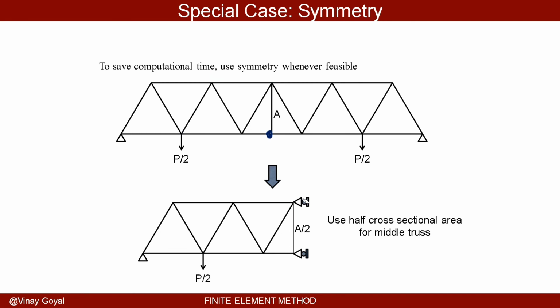In mechanics of materials, they taught you some techniques. You remove the boundary, then you assume that the boundary moves, and you impose a reaction force equal to something. So yes, this will always give you an answer. You can constrain as much as you want, but you always get a good answer. You can always have situations where it's overly constrained and Abaqus will not solve it, but for the problems that I'm discussing today, it should be very, very doable, and you should be able to get an answer.